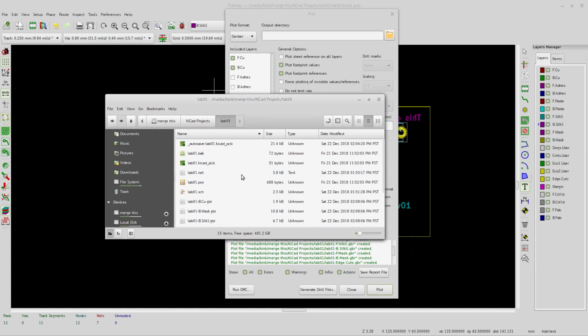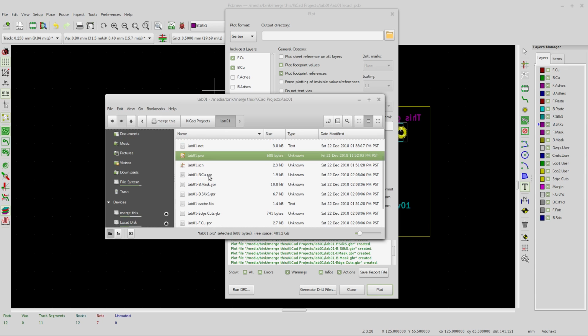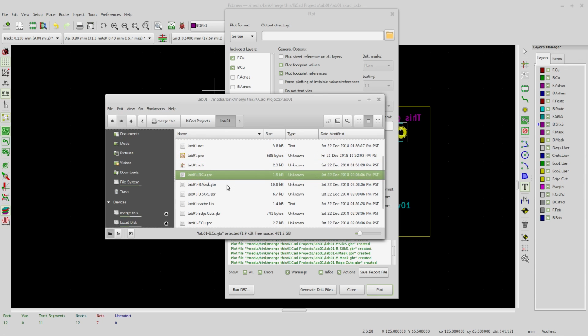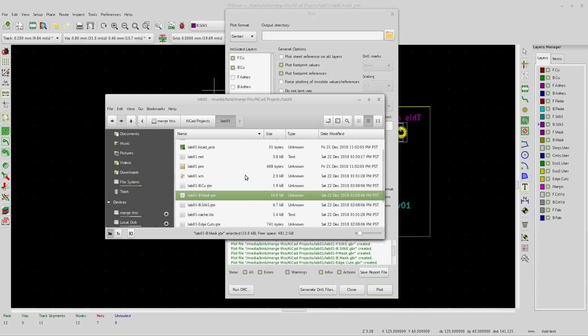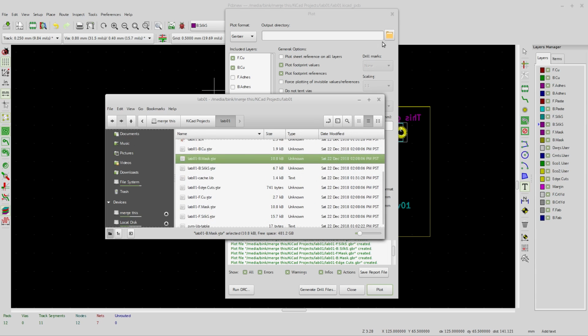in the folder that's got the PCB, it's all kind of a mess right now. It started as a .pro and a schematic and a PCB. Now we've got a net list in here, and a library backup in there somewhere. But here's all my Gerber, GBR, files. Each one of those things we checked is a separate layer, you see? We're going to have to deal with that in a second because the board house doesn't want all these things as separate files.